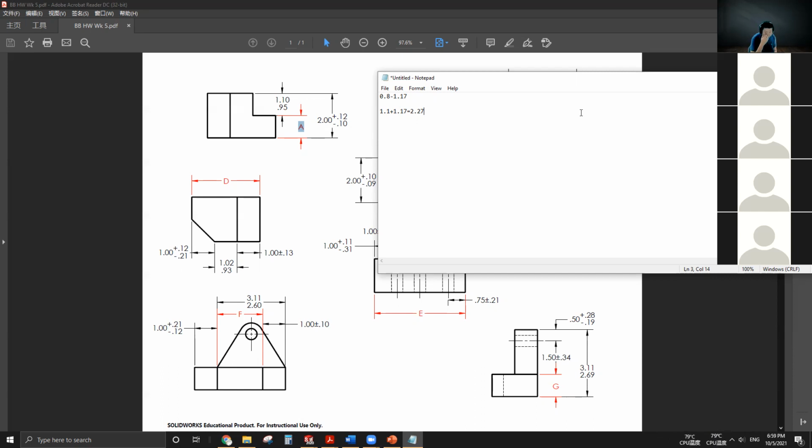So this is what I want to show you guys. Normally, if you define the overall length, and this length contains different sublengths, you need to leave at least one section alone, because if you define every single section and then you define the overall length, that's over defining. So one of the very important rules of dimensioning is never over dimension, never put two dimensions on one subject, because they're going to conflict.